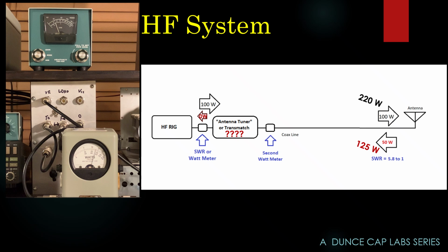My reflected power coming off the tuner is near zero. That means this 100 watts, as it bounces back and forth, can't be absorbed here. This is all reactive. Every time it goes to the antenna, half is absorbed, half is reflected. After this happens several times, you end up with virtually all of the power absorbed by the antenna. We have now invented a system that is almost 100% efficient at getting that antenna to take all 100 watts.